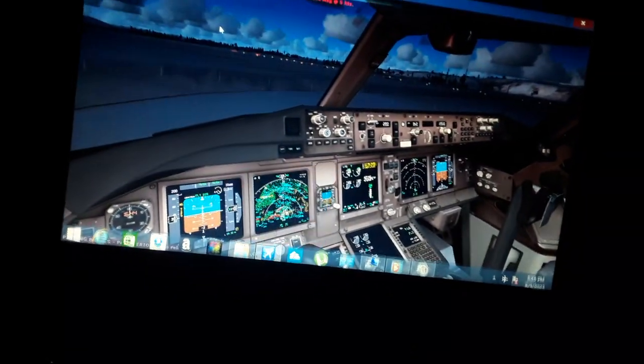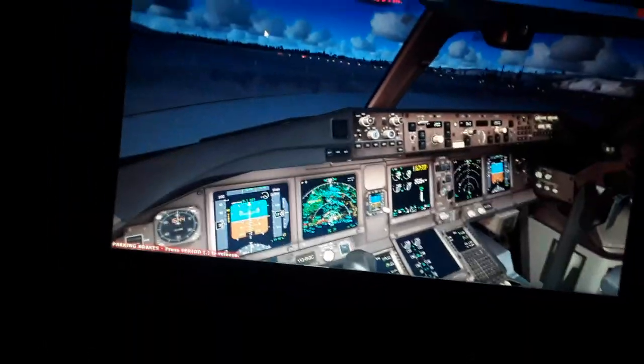We're going to have intermediate waypoints and fixes, and also the destination airport and runway. We're going to use the STARs, the standard terminal arrival waypoints and fixes, and also the ILS localizer frequency of the destination runway and airport. We're going to select the horizontal localizer and the vertical glide slope. It's going to guide you. You're going to see in the primary flight display the ILS localizer when we go mainly for landing.